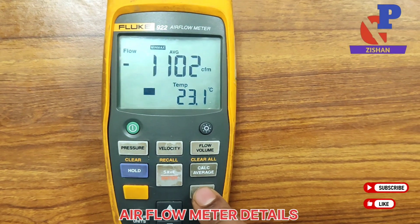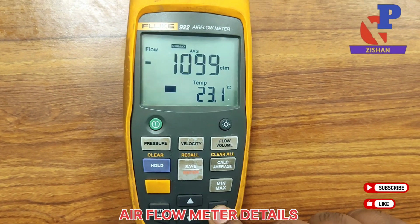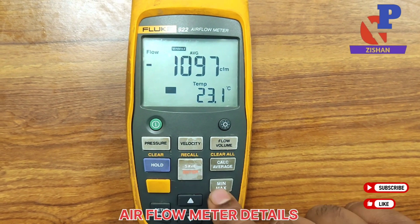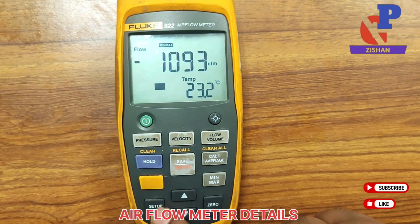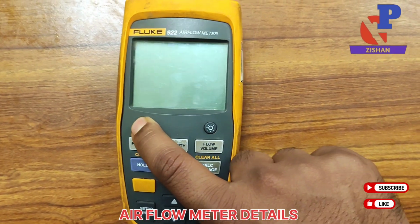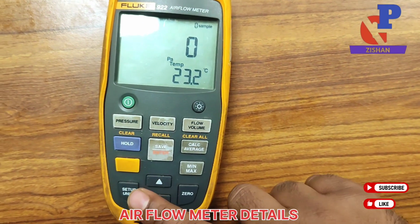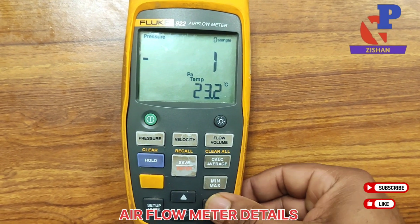By pressing maximum and minimum we can check how much the maximum flow and how much the minimum flow is inside the duct. There is also average, so we can take the average value inside the duct for all saved samples. We can change the unit by pressing the unit button.